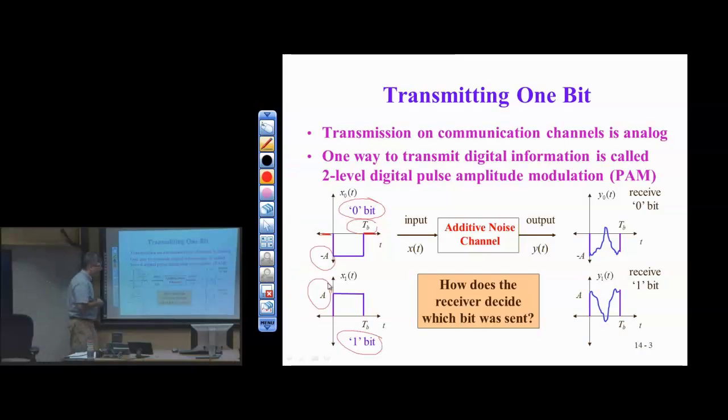Now on the receiver side, it has some work to do. So this transmitted waveform, this rectangular pulse, goes through some medium, and here we're just modeling the noise of the medium. So the additive noise is just a very simple model of the channel. We're just going to model additive noise in the channel, and really when we do this as a model in the channel, we're summing all of the independent noise sources in the system. It not only includes the channel, it may also include some analog front-end effects. So it's just an aggregate or conglomeration of all these independent noise sources.